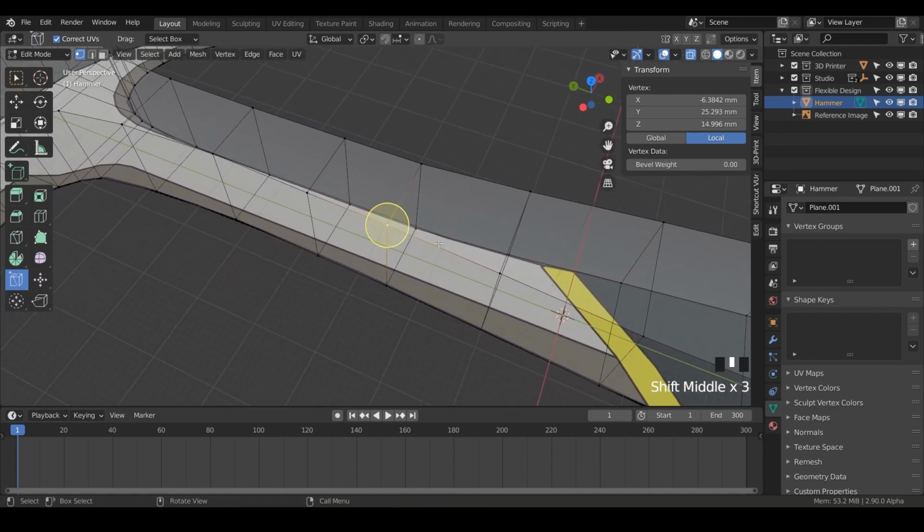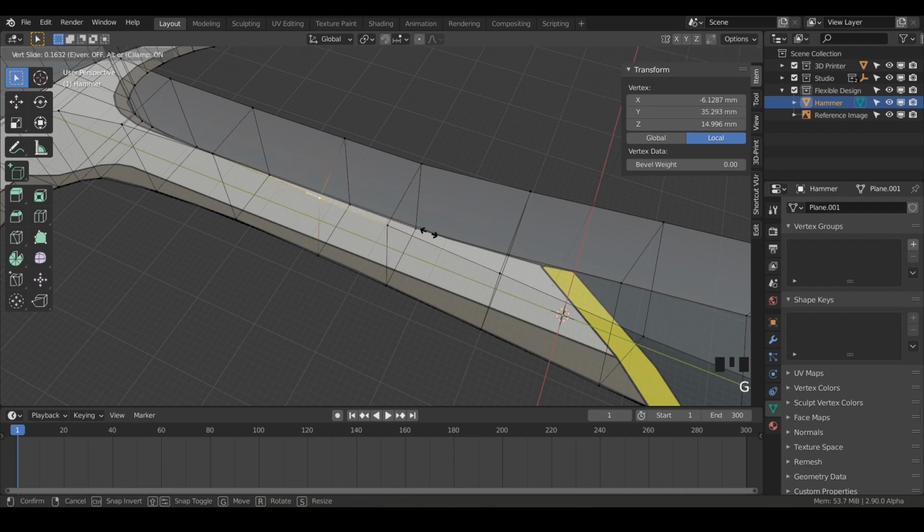You can get into vertex slide or edge slide just by tapping G twice. So say if we had just the selection tool, this is kind of how I do a lot of modeling, is just stay in my selection tool and I'll select a point and then hit GG, and that automatically puts you into vertex slide. So just one G just lets you freeform grab, but GG twice lets you go into edge slide or vertex slide. So that is what I would suggest you getting used to.